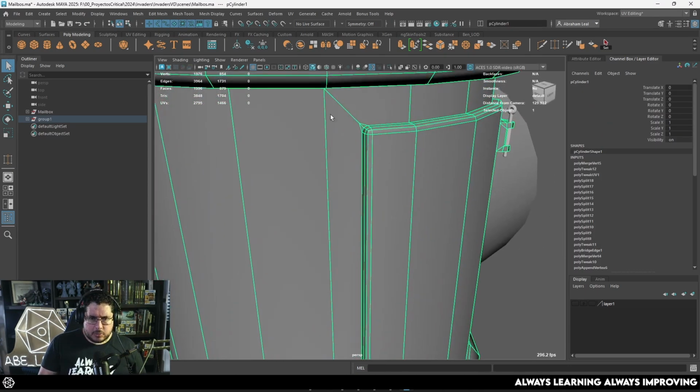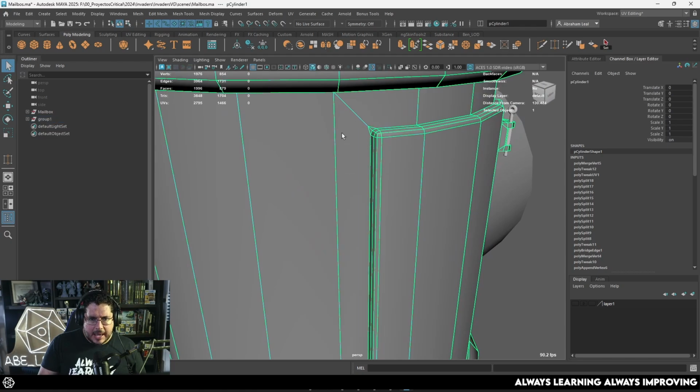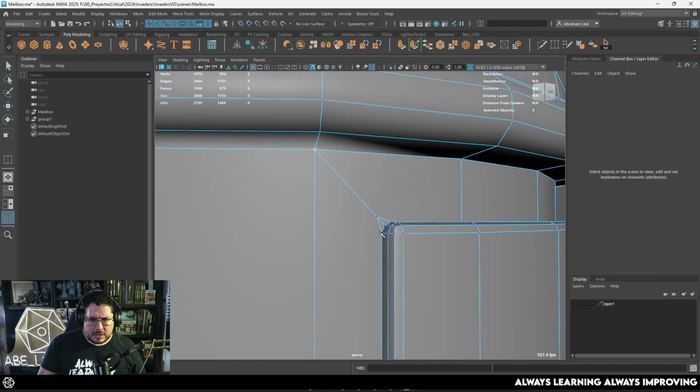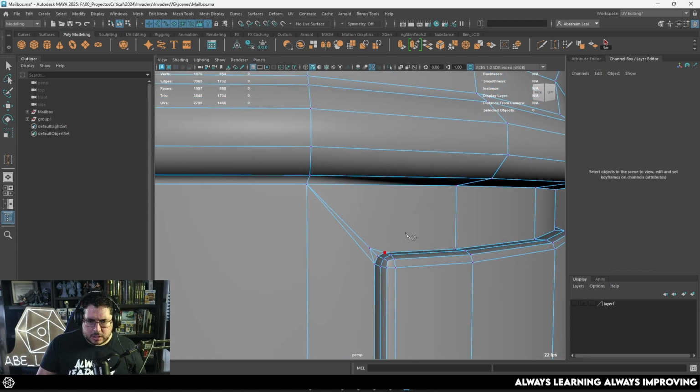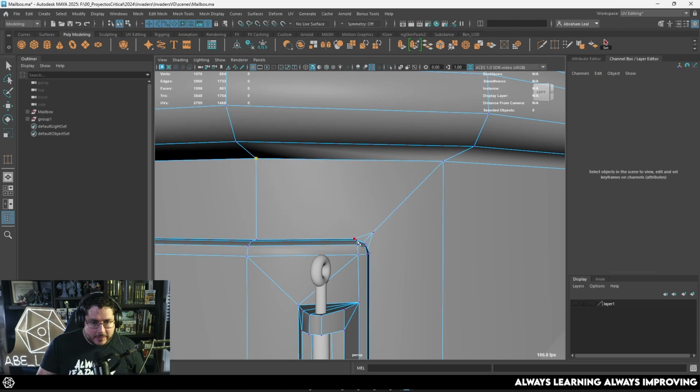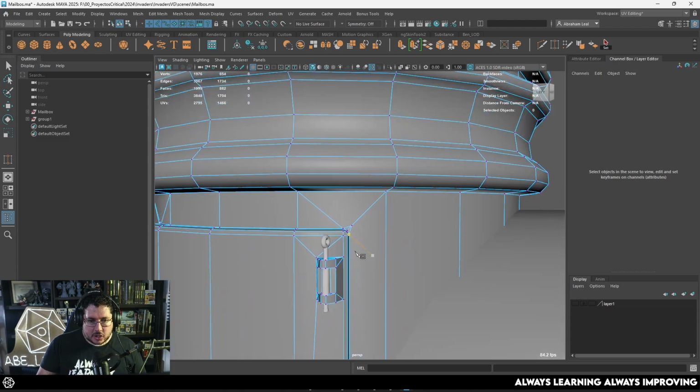We have this volume right here. As you can see, I triangulated heavily. You might need to triangulate a little bit more. So for instance, here I used a bevel, so we have an angle right there. I might need to just add a couple more triangles here on the corners so that we don't have any more angles. This is very common in assets, especially in assets that are not going to deform.